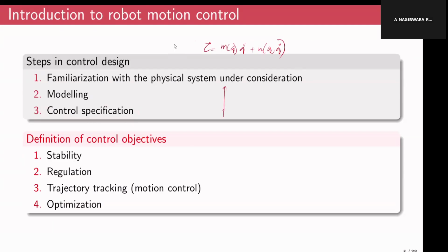For example, if our desired output is a steady output, maybe if we have a single link robot manipulator and this is our desired theta output, depending upon our controller specification, our actual output would look something like this. It would start from a zero position or some other position, and then it would gradually converge to the desired output position. So how fast should our actual position converge, and should it gradually converge? Should it converge very fast, something like this?